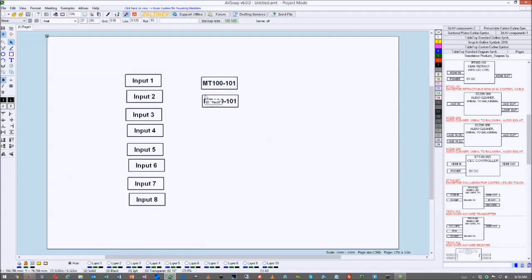Now, a couple of things also to mention about how you select the objects here. If you notice, if I click on the right-hand side and move to the left, whenever I touch an object, it gets selected. You can see how it gets selected when I touch the object.